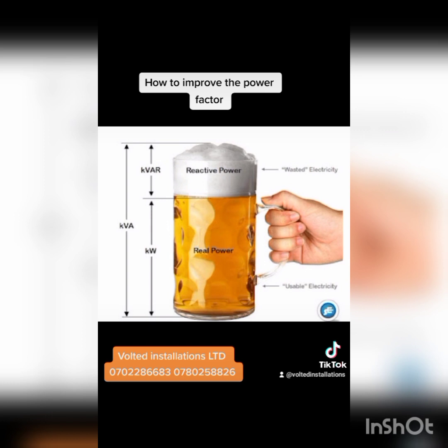Again, like I said, these are sources of reactive power. So if you're replacing them with more efficient motors, you're effectively reducing the reactive power and hence increasing your power factor.